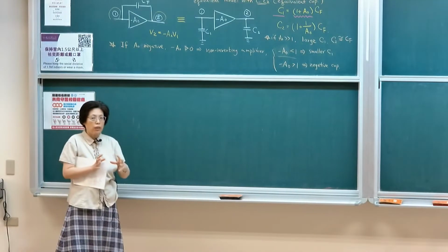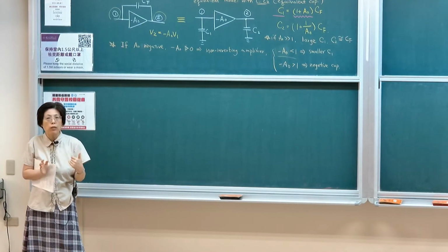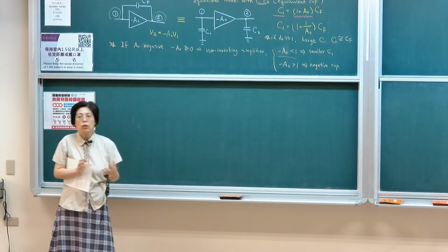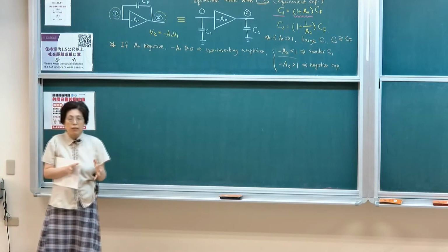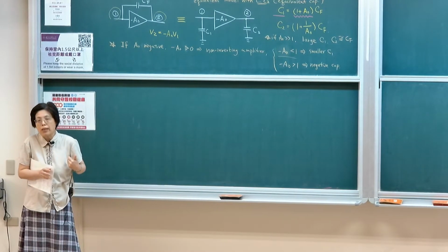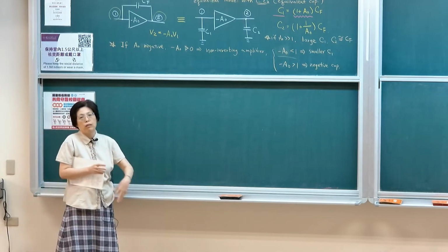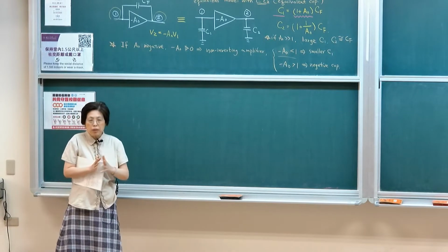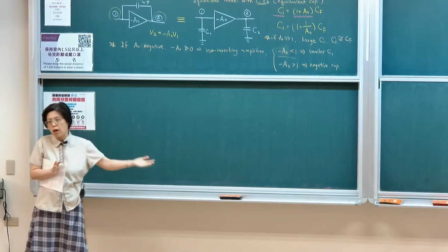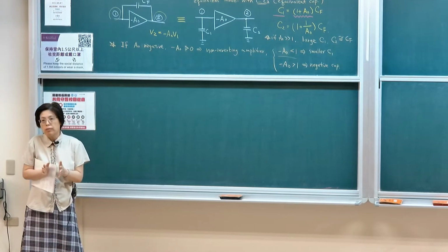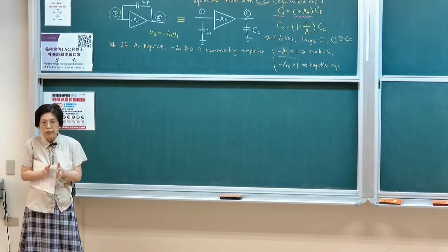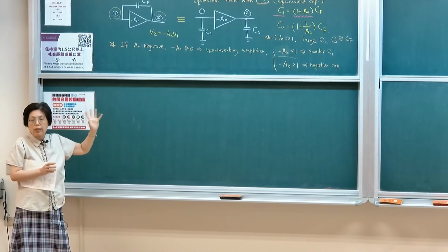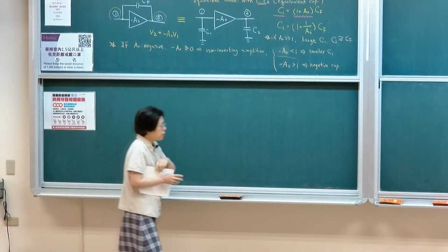In most cases when we discuss a circuit's bandwidth, what you look for is the slowest node. The slowest node means the largest capacitance, which has the highest baggage. It's like in a relay run, you look for the ones that run the slowest. This is the same for circuits. So in terms of discussing bandwidth, not for oscillating or other applications, you look for nodes with the largest capacitance, and that will happen only when feed-forward capacitances are connected across an inverting amplifier, okay?